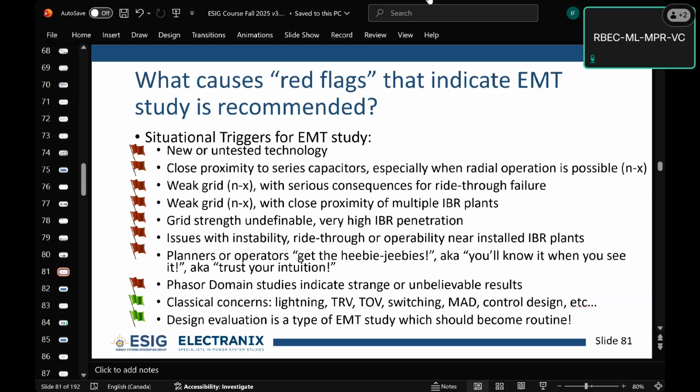So you have to trust two things. One is the models coming in, and be confident with those. The other is your study and model quality control processes, which is, how do you make your network equivalence all the time? What do your input base case checks look like? There are all kinds of quality control things that study engineers can use to at least make sure that all of the things we can compare against are matching and correct, and you get the maximum amount of confidence. But you always know, as somebody said the other day, that it's still a model.